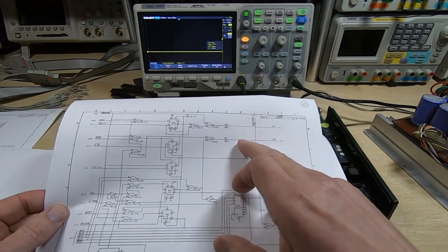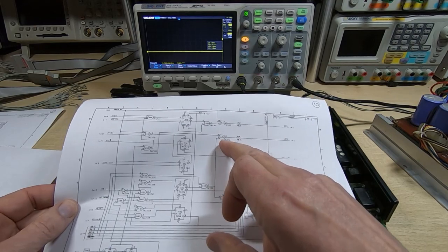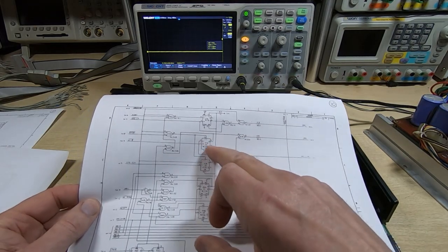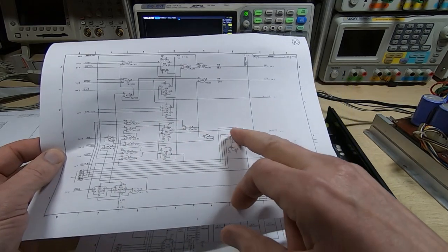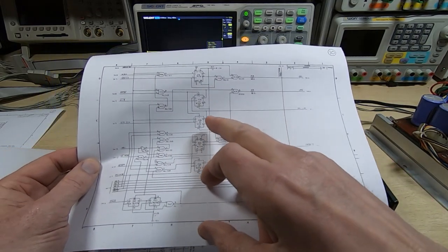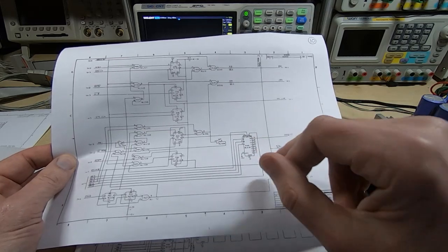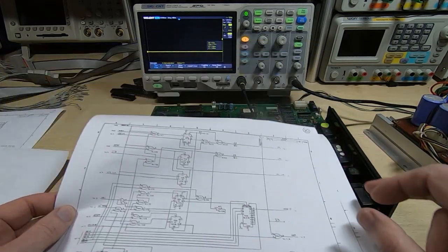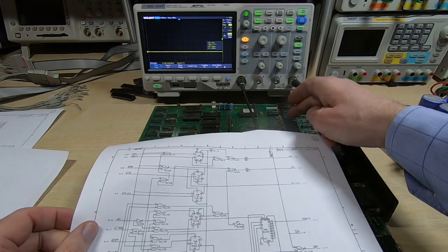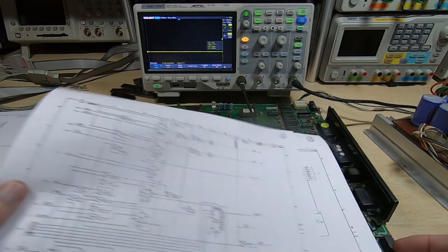So we've got the CAS coming out here. So what I'm going to do now is just work my way back through here. This part of the circuit will just be deciding what decoding to use and the sequencing for the RAS and the CAS, and the select is going to be the strobe select, the multiplex select.